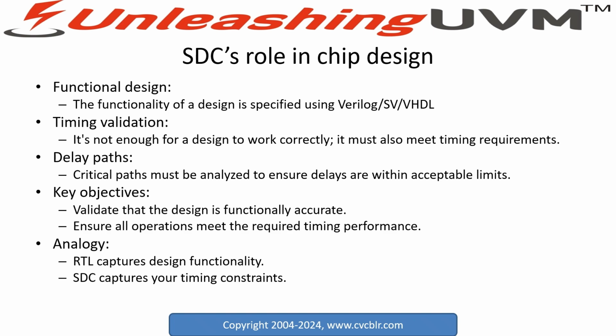The key objectives of SDC is to ensure the design is functionally accurate, and also to ensure all operations meet the required timing performance. Otherwise, your chip, which is intended to run at, let's say, 200 megahertz, may not actually work, and you will have to reduce your speed to, let's say, 150 megahertz, which is quite less compared to what your customers expect. So, if you want an analogy, RTL captures design functionality, SDC captures your timing constraints, timing requirements.